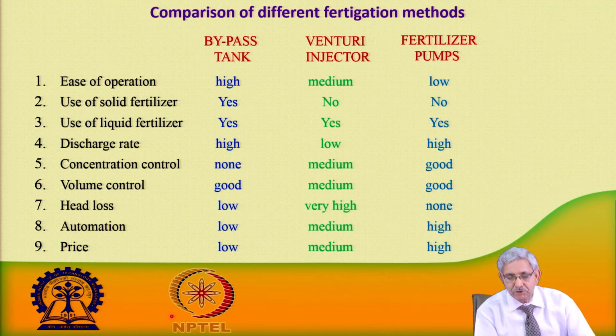Regarding use of solid fertilizer, yes, one can use solid fertilizer in the bypass tank, because water is entering all the time, so it gets dissolved. But in Venturi as well as the fertilizer pump, one cannot use it; liquid fertilizer is required.